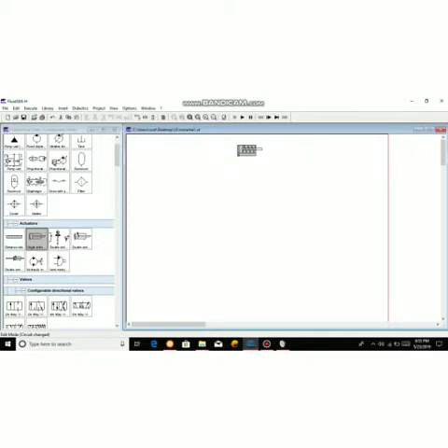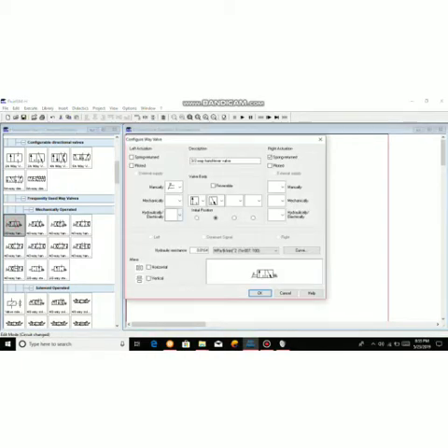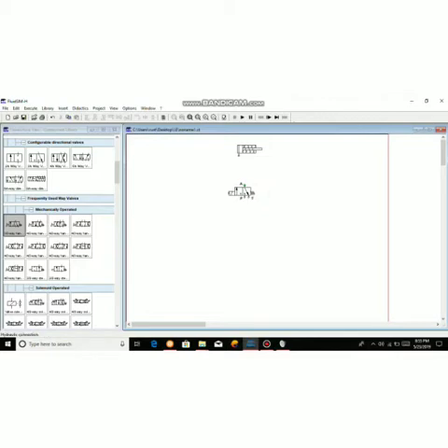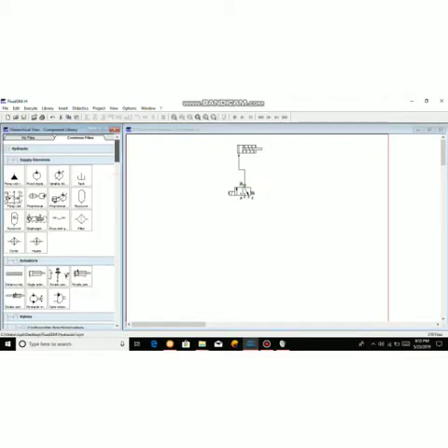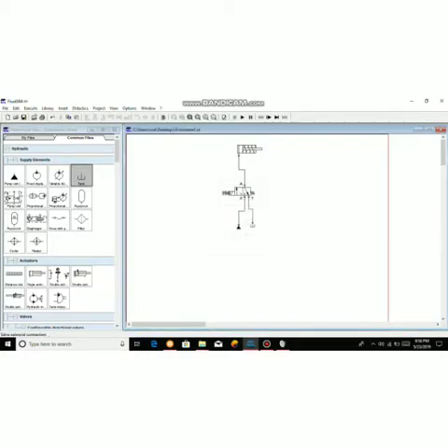And then we need to find the valve. We use the 3/2-way valve. Double click it and change it to hydraulically/electrically actuated to connect with the circuit, and disable this one. Then connect the A port from the valve to the actuator, P to the pump unit, and T to the tank. Now we double click it to label it Y0 to connect with the circuit.